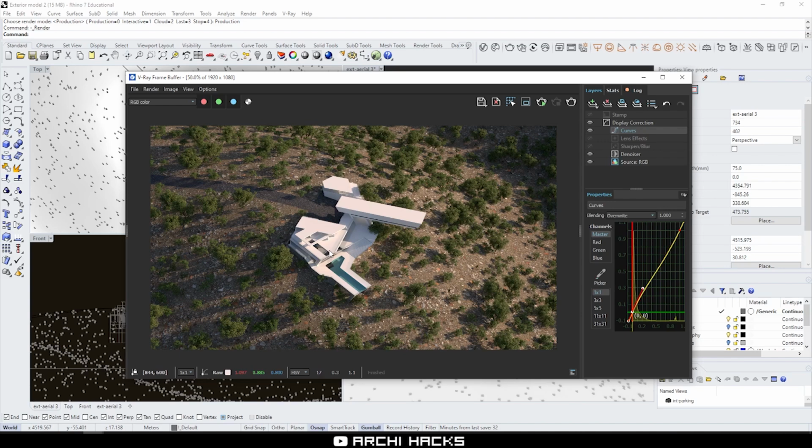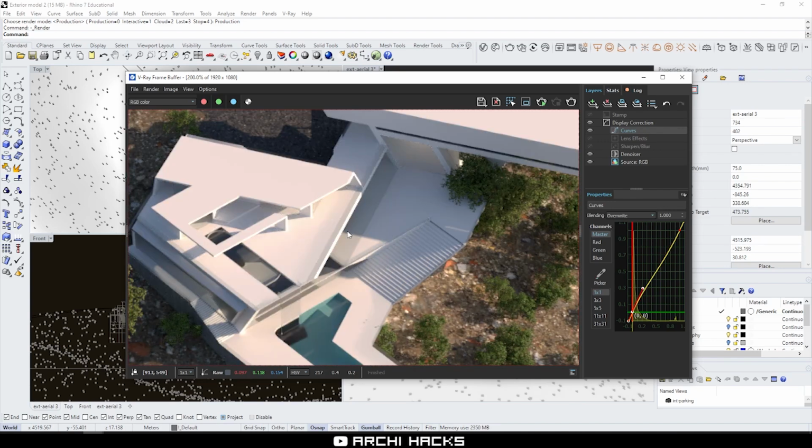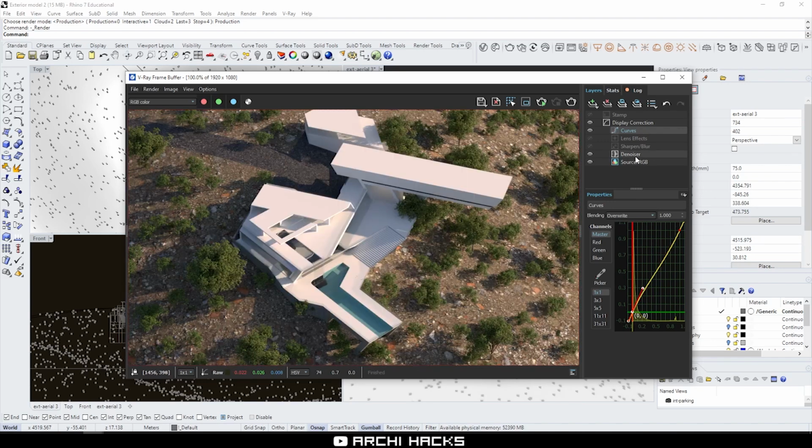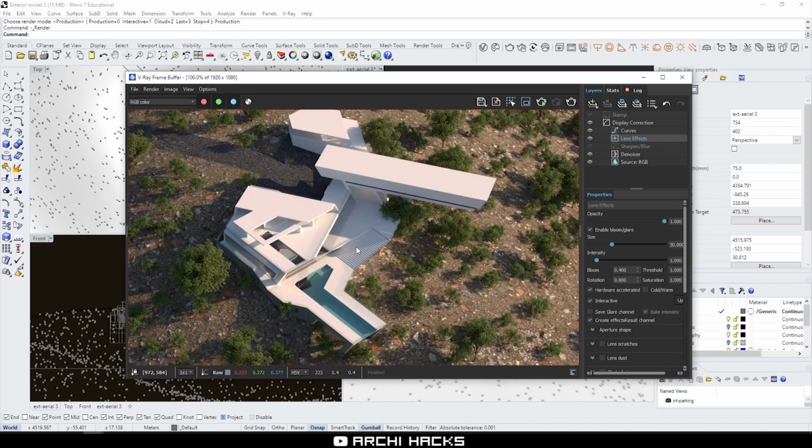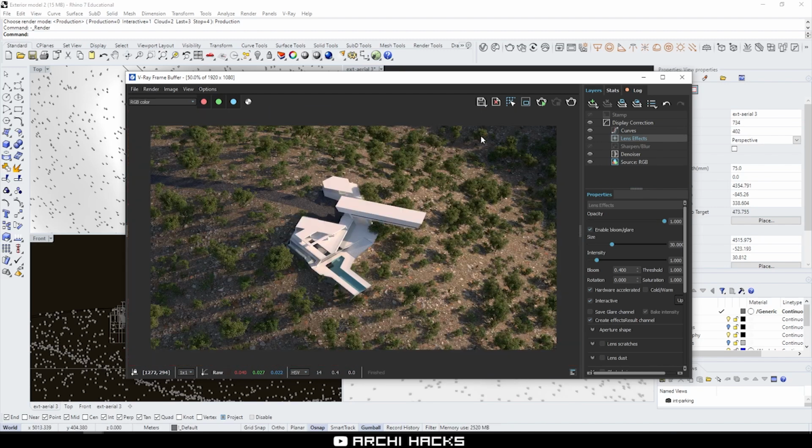And if you're using any light objects, such as the rectangular light, point light, or spherical light, the lens effect is actually really useful. You can enable this bloom slash glare, and it gives you a really realistic star and a nice little glow around the light. But unfortunately, this particular scene doesn't have any, so we're not going to see much of a difference. But if you do have some, make sure to enable this to get an optimal effect.